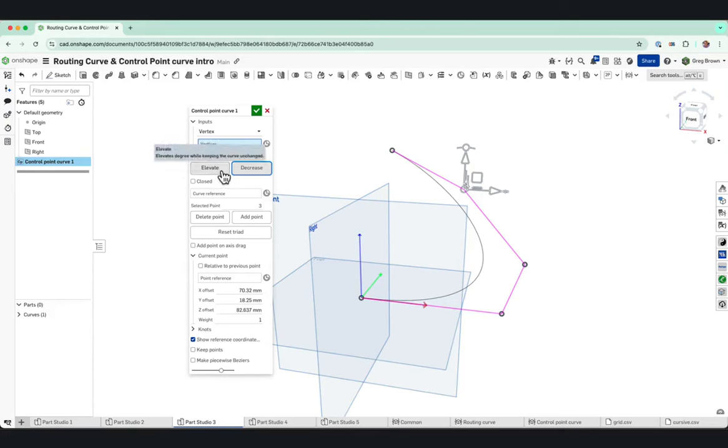Now, it's a topic for a further video, but if this was a generic NURBS curve rather than a specific Bezier curve, then the number of control points we're adding and taking away can be a little bit harder to predict. In the case of a Bezier curve like this, by increasing or elevating the degree by 1, we'll be adding 1 control point. Just note that for a generic NURBS curve that we will deal with later, that is not as easy to do. Easy to say, sorry.